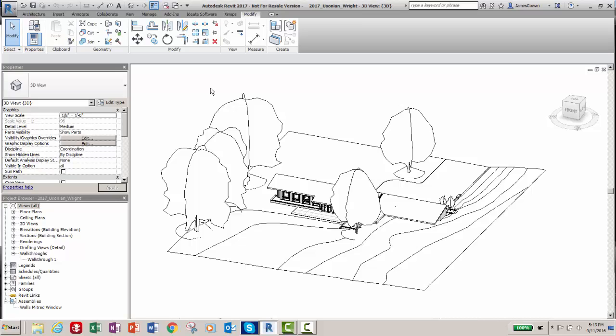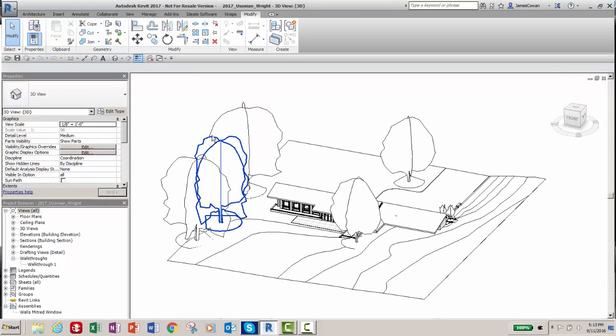When you use the product, you may choose to go this particular route, where you can right click on that quick access toolbar and say show it below the ribbon. The reason for doing that would be to give you all of this extra space so that you can keep commands down here. And that would be kind of an opening for me explaining the parts of the interface that are not so obvious.